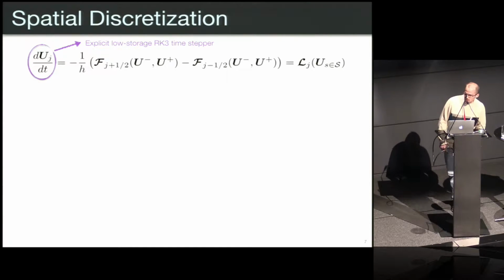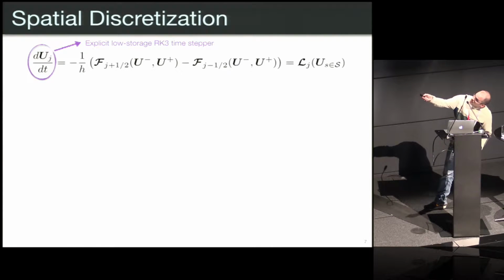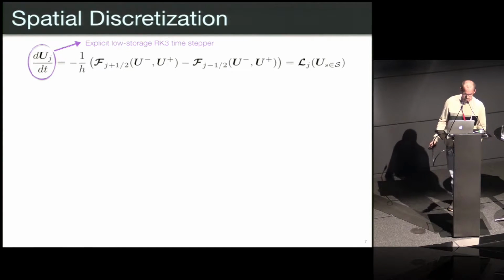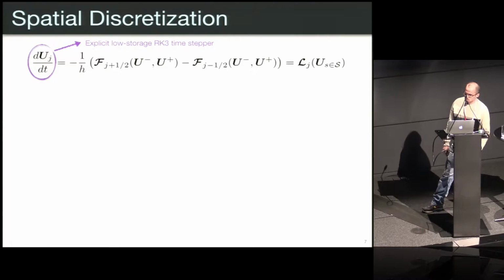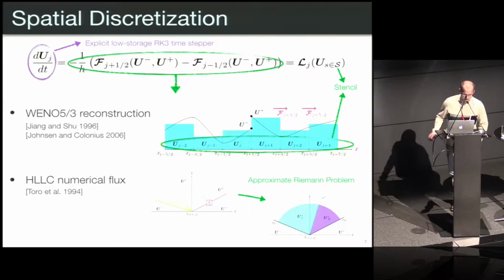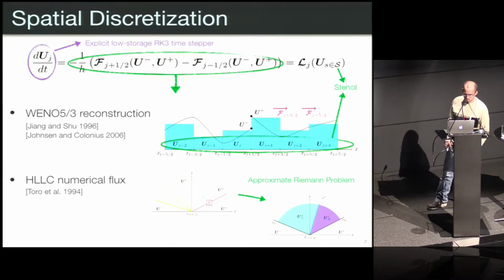So we use a method of lines to discretize the system of partial differential equations, where we discretize the right-hand side using a finite volume method, as mentioned before, which will reduce the system to a system of ordinary time-continuous differential equations. And one of the key parts of our solver is to compute this right-hand side, which consists of mainly 2 parts.